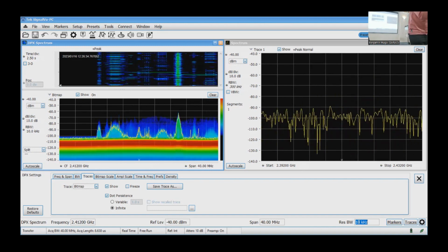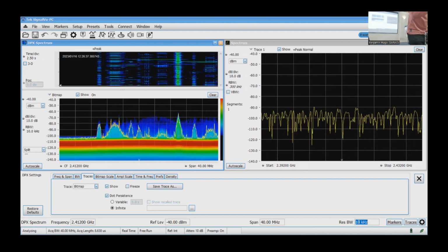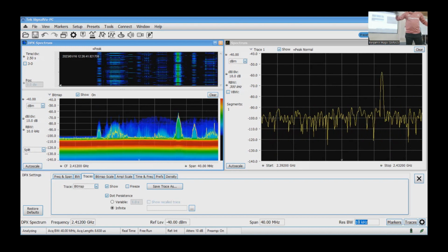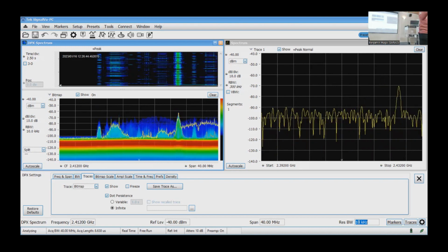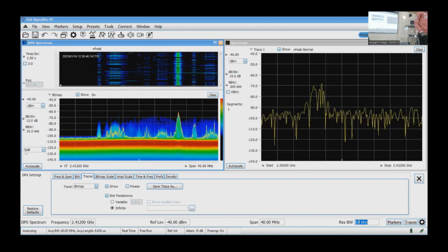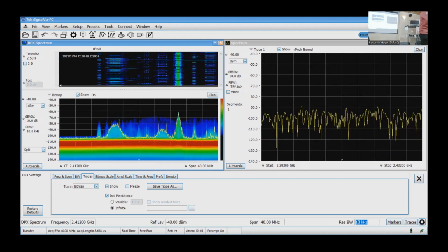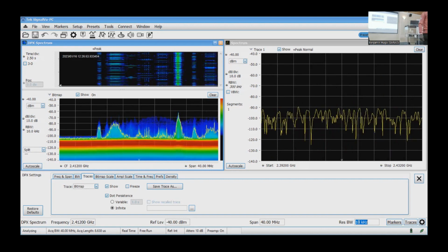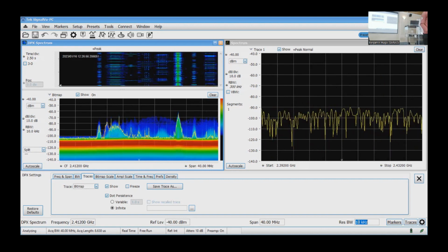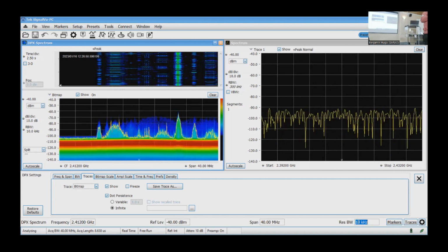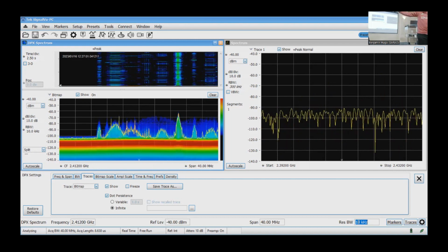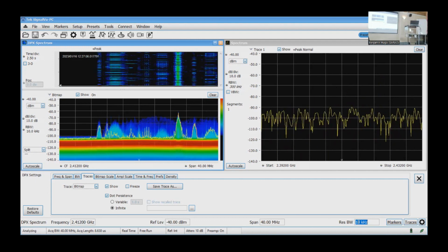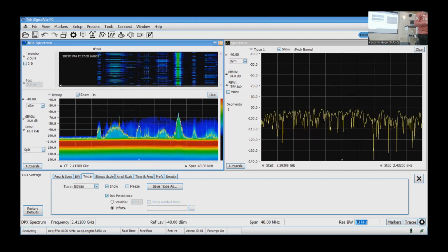And these are for field measurements. Now, this one here and that one, we have bought them, and they're very expensive, by the way. So we need students to characterize them. We don't have a facility for characterization, which is an anechoic chamber, but we can borrow through collaboration the facility at Stellenbosch University. Then we need students to go and characterize the antennas and tell us that the data provided by the manufacturer is actually true. That's a student project.